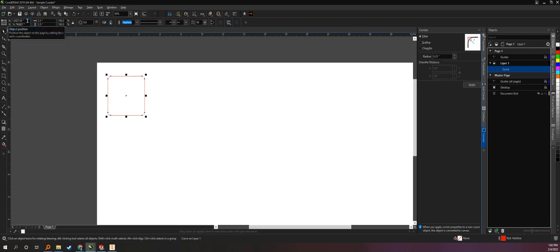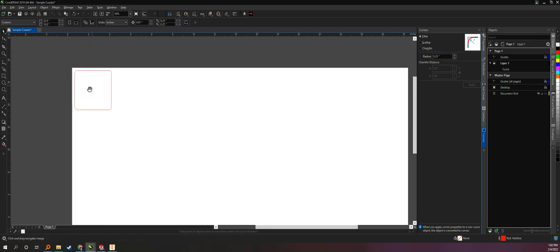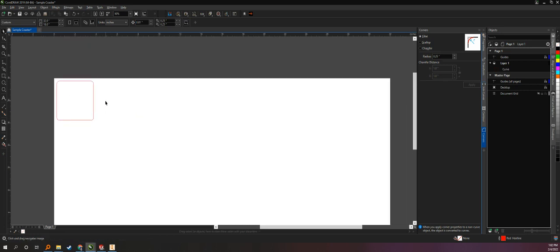And I'll just manually type in 0.25 for the X, and then for the Y, since it's 18 inches tall, put that at 17.75. Now we're good to go. So that is simple shape, simple coaster cutout. In the next video, I'll be talking about images and how to engrave things on your laser.